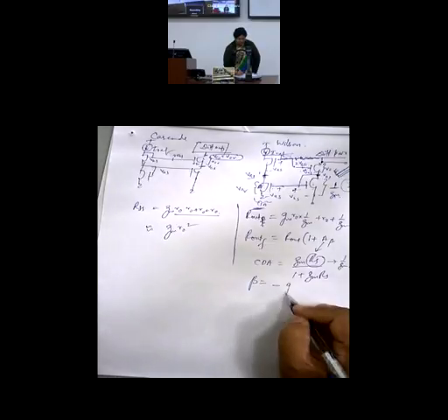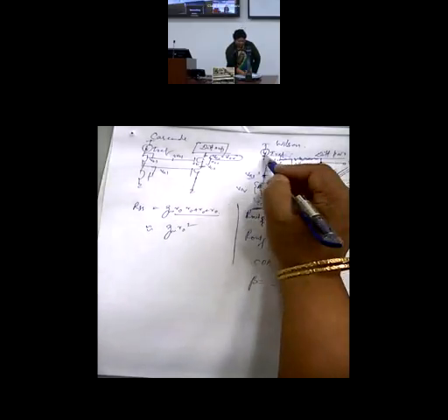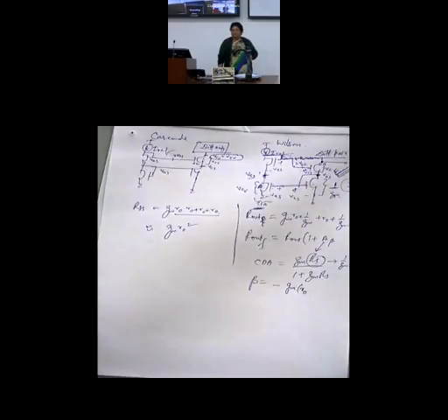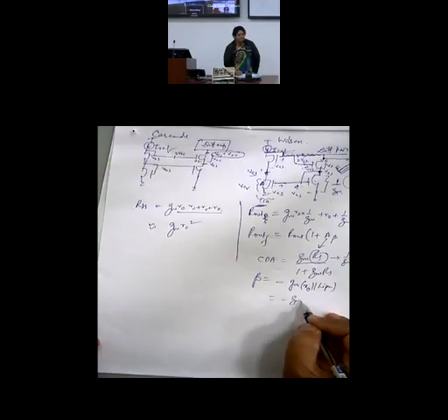Minus GM times R. This is diode connection, so it would be 1 by GM plus R. IREF, assume it's giving you high impedance, infinity or a very high value. So a very high value means GM RO in parallel. This will be roughly minus GM R.